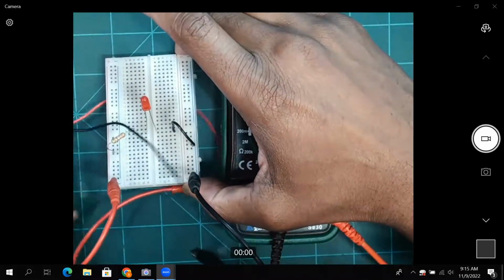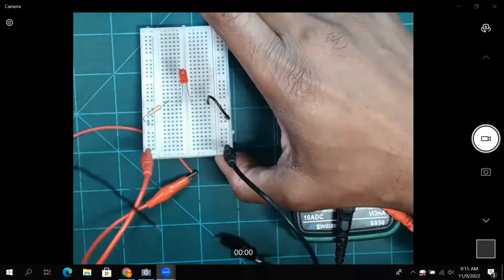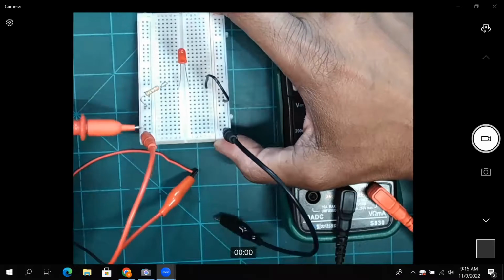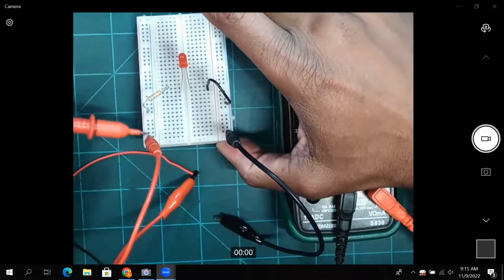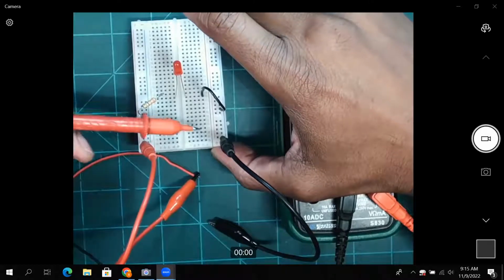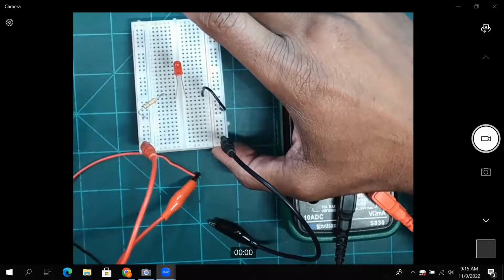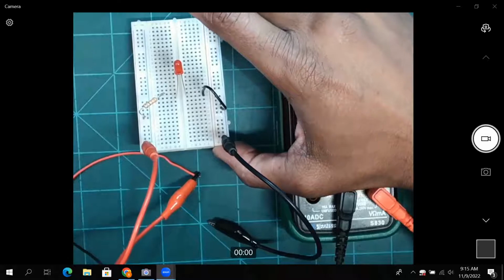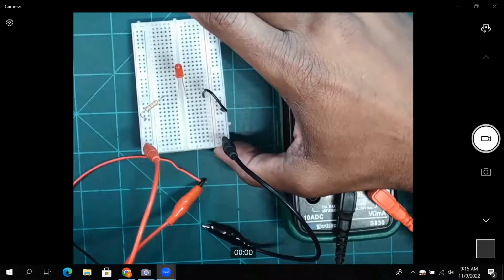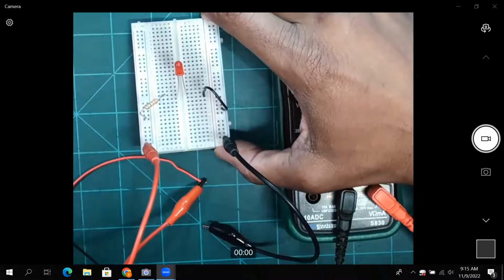All right, so here's my battery. There it is. And in your case, you're going to have a power source, and this battery is going into these 2 ports right here on my breadboard. So when I measure the voltage at my battery, if it's a fully charged battery, I should get 9 volts. But if it's drained a little bit, it's going to be under 9 volts, right?